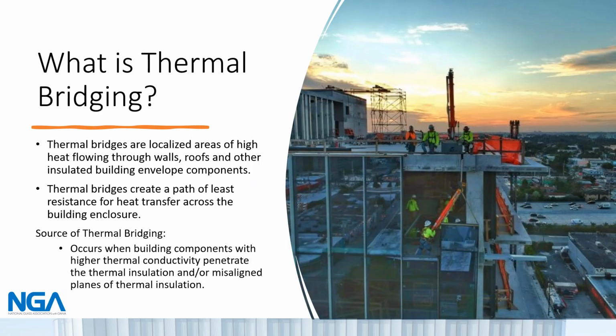So what is thermal bridging? We mentioned on the previous slide, it creates the path of least resistance for heat transfer. In more detail, thermal bridges are localized areas of high heat flow through walls, roofs, and other insulated building envelope components. Thermal bridging is caused by highly conductive elements that penetrate the thermal insulation and/or misaligned planes of thermal insulation. These paths allow heat flow to bypass the insulating layer and reduce the effectiveness of the insulation.